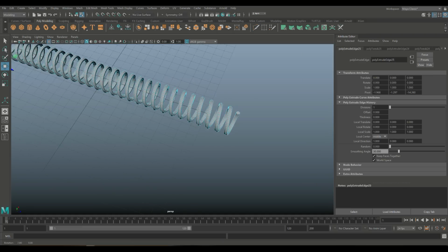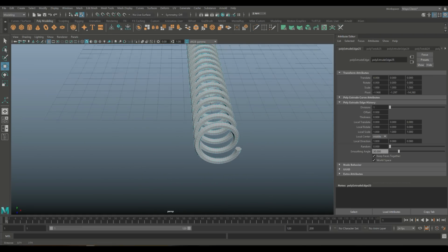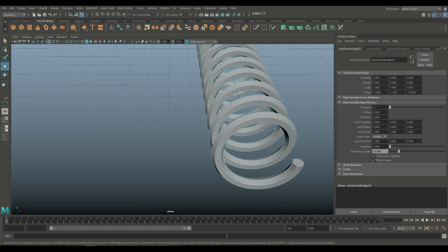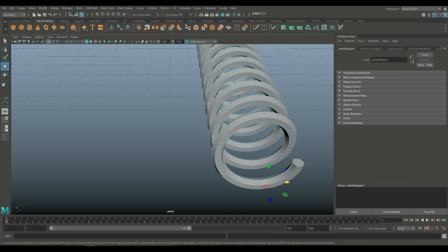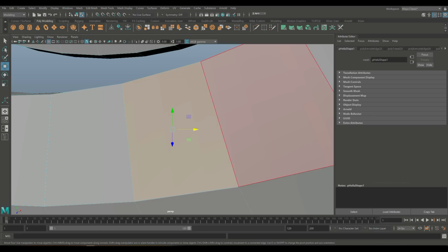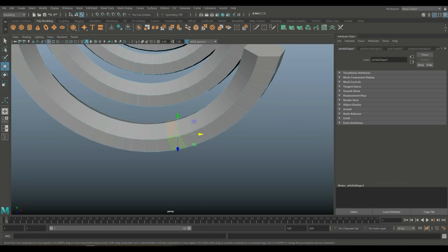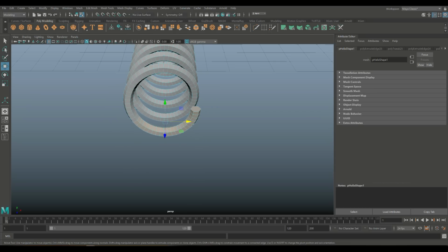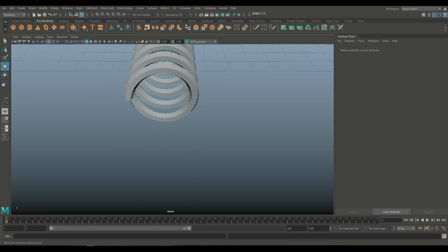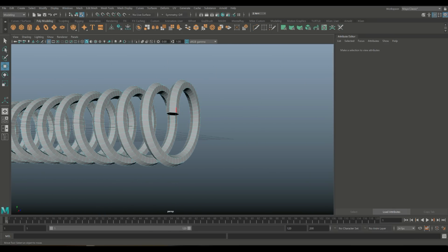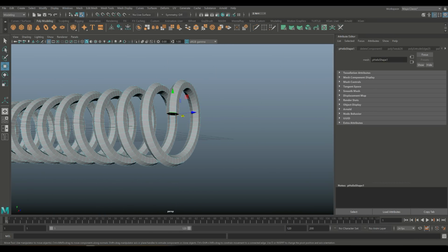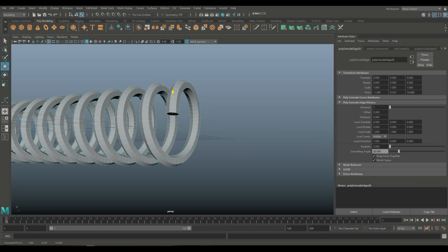Let's jump to the other end here, and let's see where we're going to put that one. Different place. Let's go in the face here, and we'll take this and double click on this. We'll hit Shift period to increase that selection. And delete that. And then from there, we're going to go in to edge, double click, Control E to extrude, and we're going to do this manually.